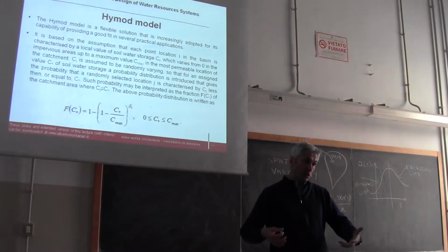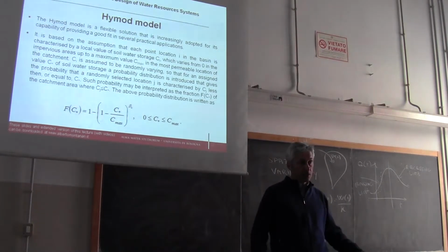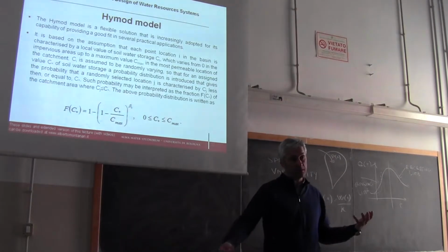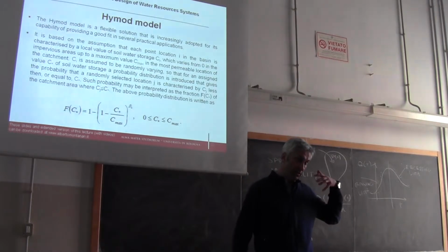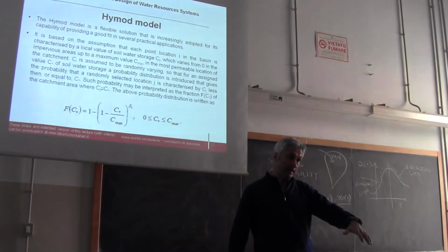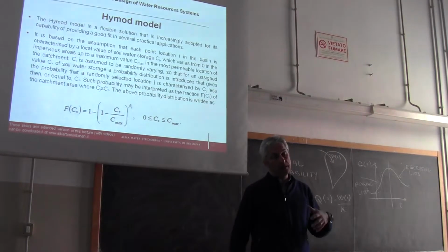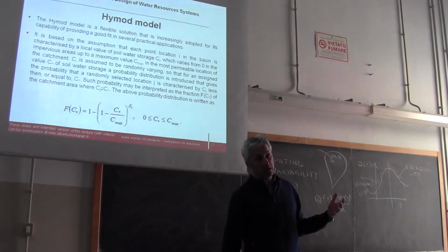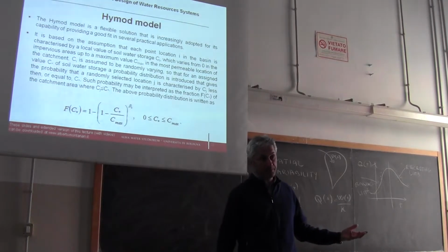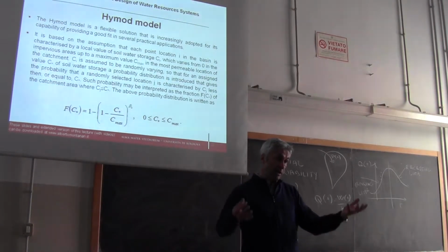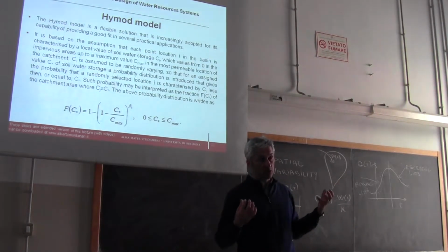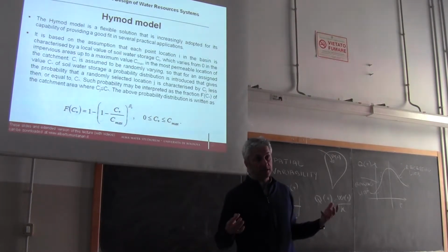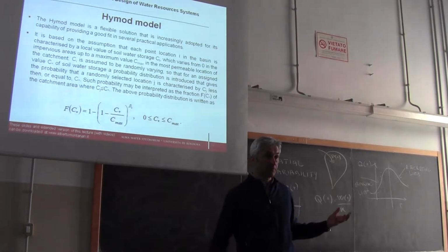If you go over the hill slope, the soil is far from the river. It's steeper, and therefore you have more underground flow that frees soil storage, so the areas are typically not saturated. And if you go up in the mountains, it's more likely that you get rocky soils that don't absorb water and get very easily saturated. So you understand that everything is spatially variable.